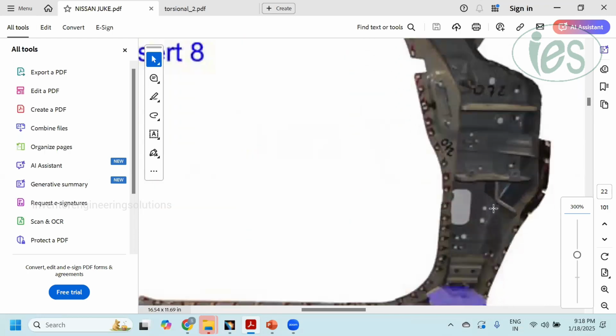In the A pillar parts, in this area, the upper hinge will be fitted. This is the bracket they added for the upper hinge mounting. In the pillar area, they keep the reinforcement just inside the pillar.